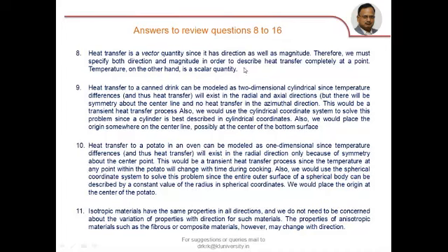Heat transfer is a vector quantity since it has direction as well as magnitude. On the other hand, temperature is a scalar quantity. If you take a canned drink, you can model it as a cylindrical problem and a two-dimensional one because the temperature difference exists in the radial direction and also in the axial direction.